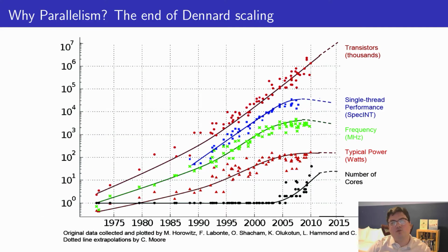Looking at historical trends, there used to be only a single core in CPUs until about 2005. The increase in CPU frequency and single-threaded performance started to slow around 2005. The capping of CPU frequency, coupled with the introduction of more cores, enabled an increase in the processing capability of CPUs while keeping the power consumption in check. This is why we see nowadays CPUs with dozens of cores.